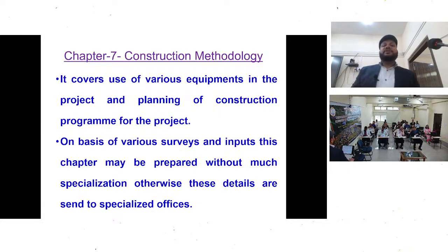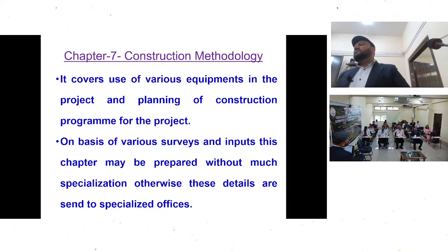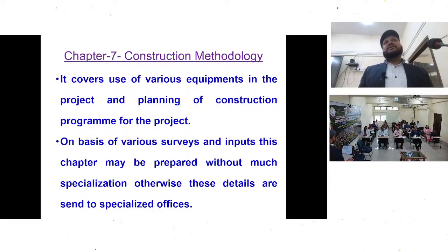Then construction methodology: which type of methodology we will use in project planning and construction, and different bar charts have been drawn, using the CPM PERT method, so that how much time will be required in completing the project will be reflected in tendering. Because if it is not studied in detail in DPR preparation, then there will be difficulty at the time of tendering, and there will be a lot of litigation and other things.